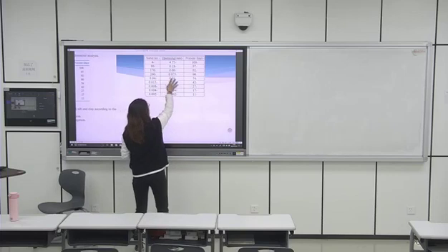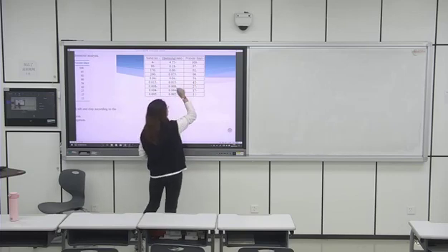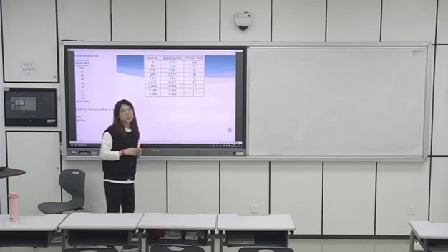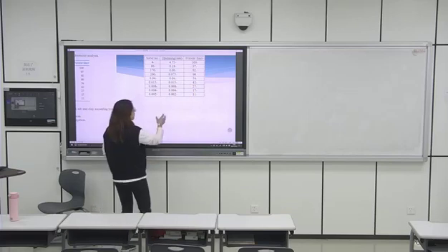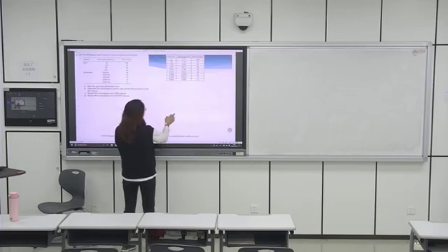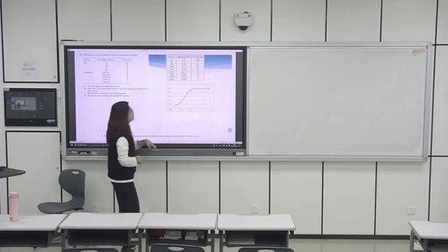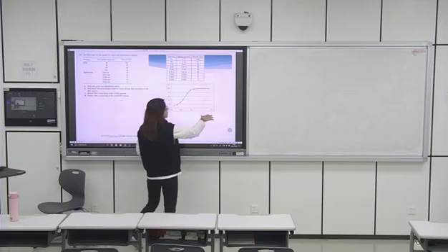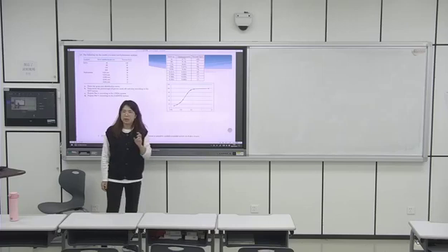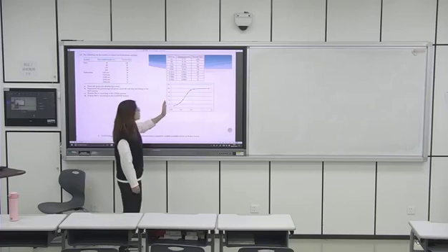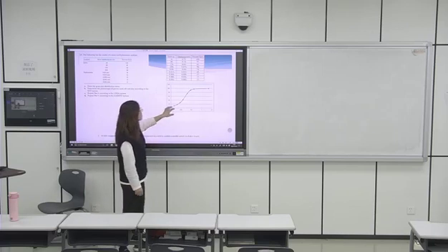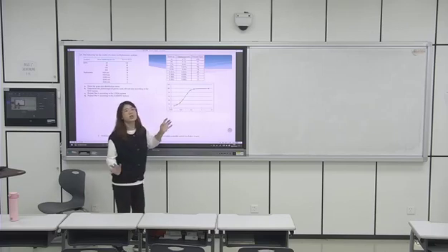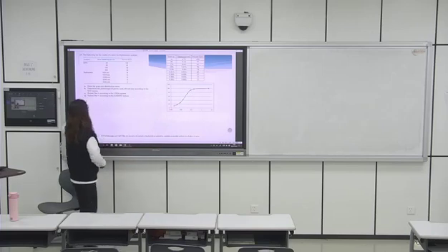So then you know the opening and you know the percent finer, and then what's the particle size distribution curve? The particle size distribution curve is actually the relationship between these two. If you plot it, the x-axis is the opening, or we say particle size, and the y-axis is the accumulated percentage. Then just plot those points here, that's all. So then let's see B, C, D.